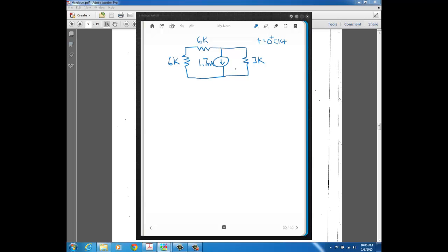So all we're left with is what you see here, and the key point is that with inductors, it's current that can't change instantaneously. So whatever current that inductor had right before the switch changed, it's going to have the same current just after. In the previous problem we had a capacitor, and with capacitors it's the voltage that doesn't change abruptly. So once we found that there was 95 volts across that capacitor before the switch changed from position 1 to position 2, it still had 95 volts across it just after the switch changed to position 2, and that's why we represented that capacitor with the 95 volt voltage source.